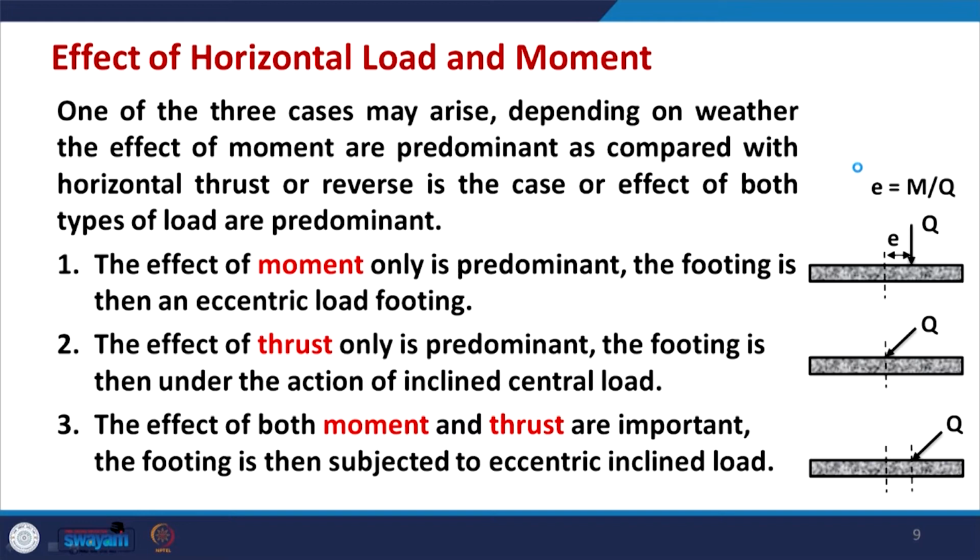Let us consider the first case where, due to earthquake load, not only do you have vertical load, but you have some moment also acting on the top of the foundation, maybe due to the superstructure load. So the foundation is not only subjected to vertical load, it is also subjected to moments, and you need to design your foundation for both.